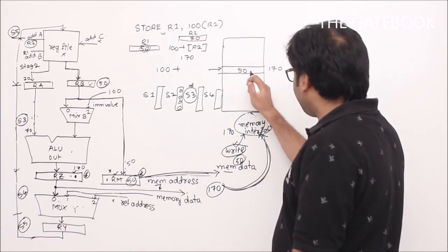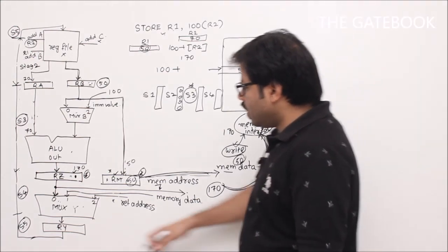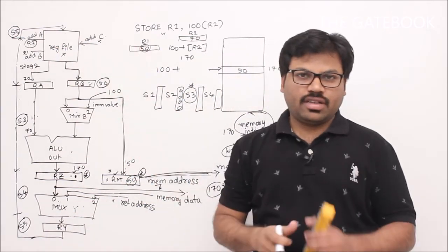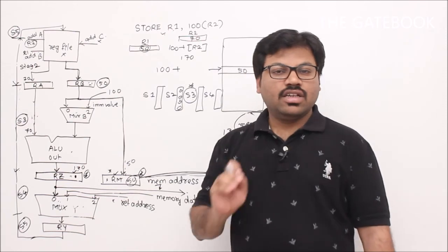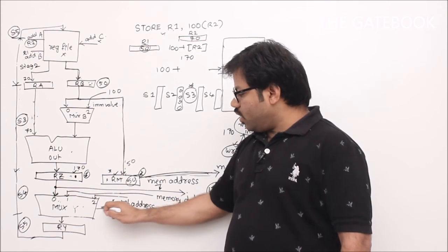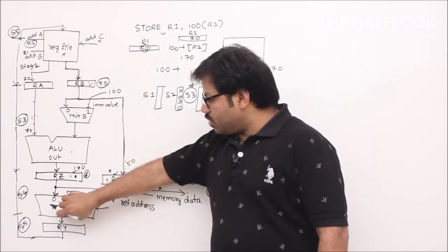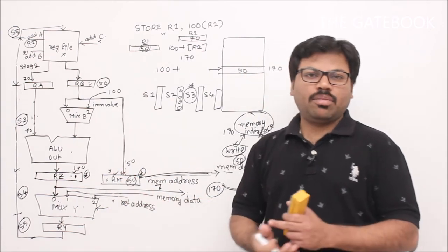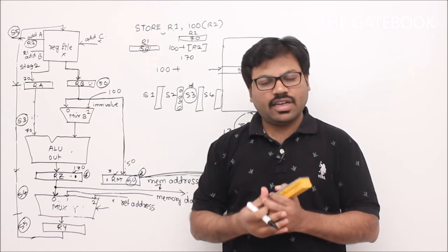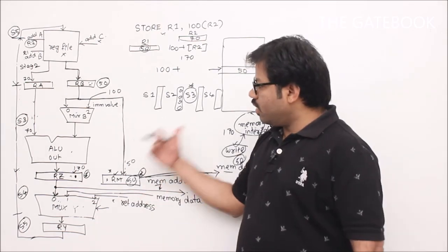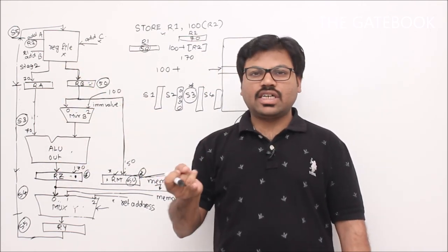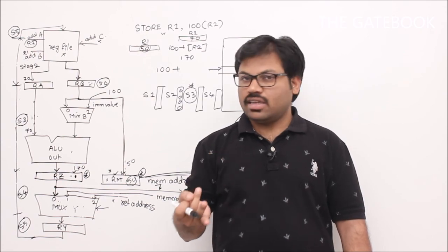But that 50 here, nothing. So that means there is no purpose, that means we don't use it, right? So that's why in the register file we don't store anything. So that step is unnecessary. Sir, but the data will flow, right? We have to control it. That's why there will be a signal such that this multiplexer will be disabled. We have to disable that multiplexer so that it will not work and will not send the data to the register file. We can plan it. That is a separate issue, but at least you are now learning how this small circuit is going to do the load instruction, store instruction, and add instruction, everything, correct?